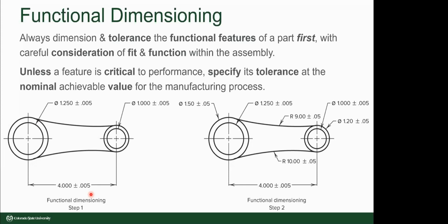Internal diameter of the holes, yes, that is definitely critical, because the way that they mate to the shafts is certainly very important. And the distance between the hole centers, another critical dimension to make sure that the functionality once the shafts are installed works as intended. Perfect. So those are our critical dimensions. They've been dimensioned in this left-hand view of the linkage bar.